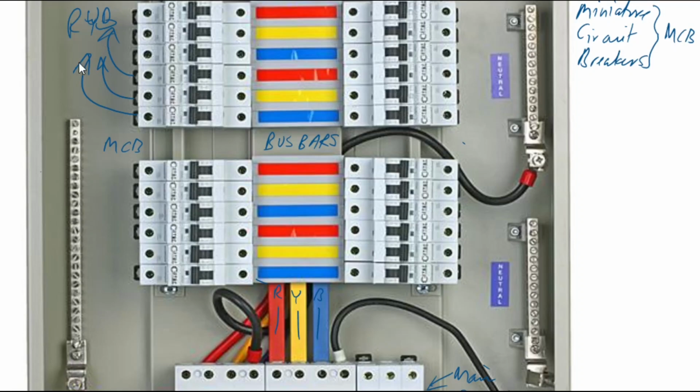So for every phase that is connected, you can tap a neutral from any of these points. These are screw heads. So you would have your conductor being connected here, and the exposed part of the head is tightly connected to that bar. The neutrals are exposed because you do not need insulation, as the neutral provides a return path.